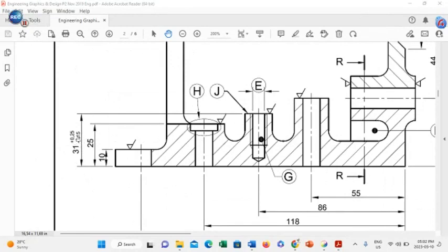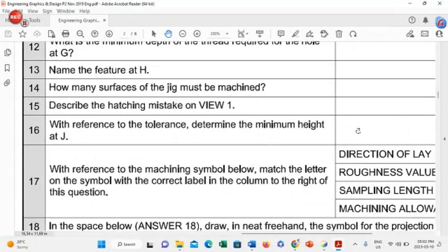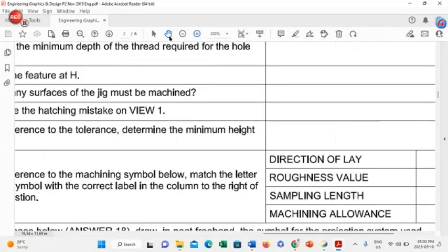The plus is the upper or maximum. If you should request to write in the upper or maximum, which is 31 plus 0.25, gives you an answer of 31.25. But that is not the answer requested in this particular instance. You are requested the minimum. So you will have to take 31 minus 0.15, which basically leaves you with 30.85. And 30.85 is what you are going to write in here.